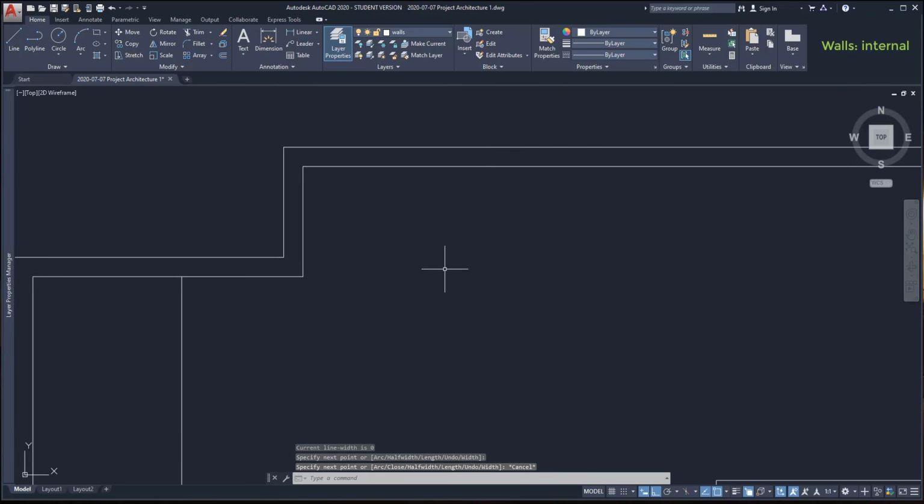Then let's make the internal outline of the laundry room, using the dimensions from the PDF file. Press Enter to use the polyline again. Now I type 2050 mm to the right. Then this line has a length of 3400. Next, I can move that endpoint. It's possible to do this even in the ortho mode. Then I go down and click on this intersection. Finally, I'm going to connect to the endpoint.